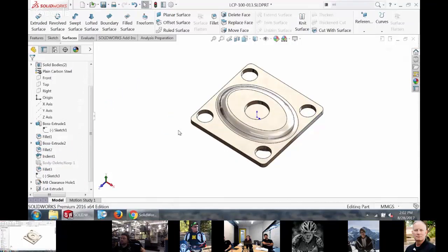I have no errors. But that doesn't mean that I'm done. Not all errors are going to show up with an error, kind of like that really thin wall error that I was getting before, where it wasn't going to tell me until I looked at it. I had to draw attention. I could run that thickness tool.